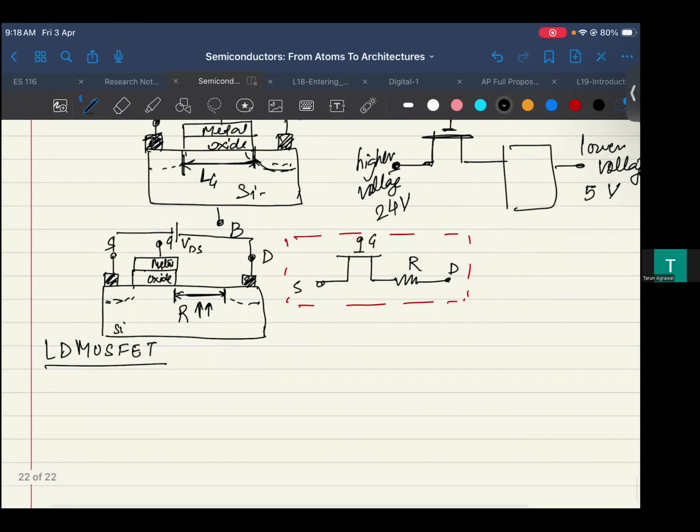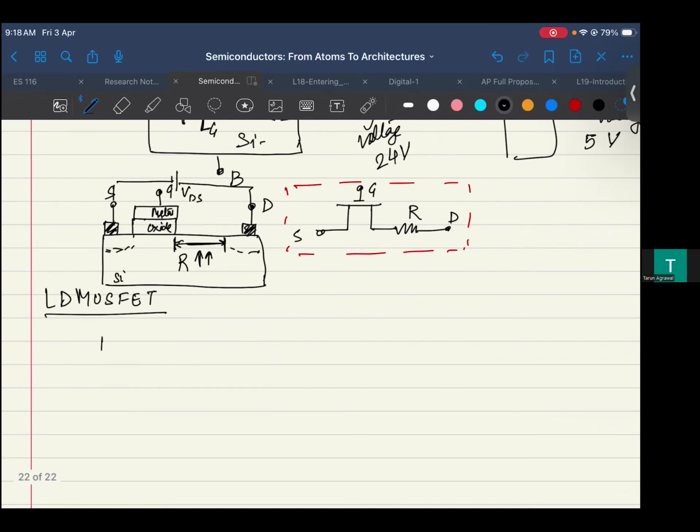There is another. So this can also still hold a certain voltage, but let's say we are talking about very high voltages. For example, we are talking about 1,000 volt, right? Now, will this structure be able to hold it? We may keep increasing, but it can do only so much. So then you use another dimension, which is, let's say, why? Because this silicon substrate anyway is very thick. If we are talking about a 12-inch wafer, right? The thickness of silicon would be around 775 micron or so, right? So that is very large, or 0.7 mm, right? So that is a large thickness for the transistor.